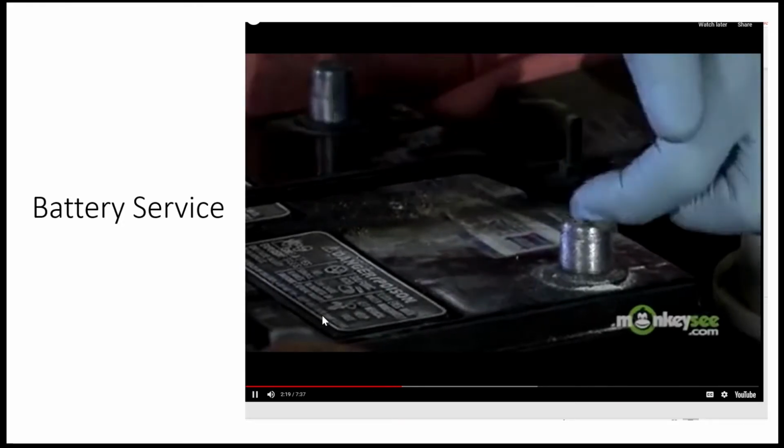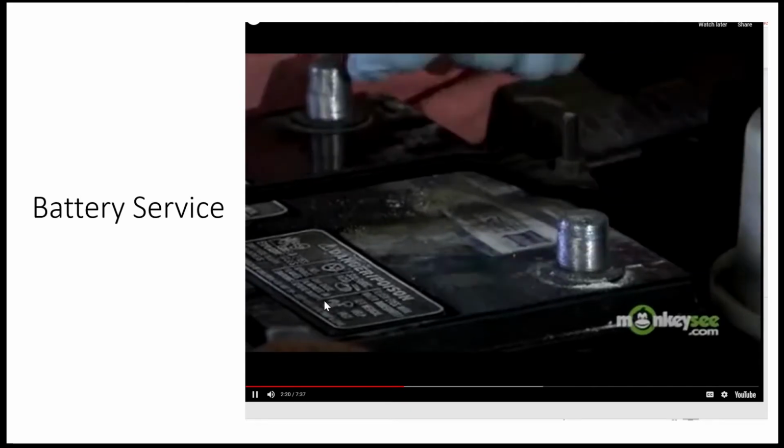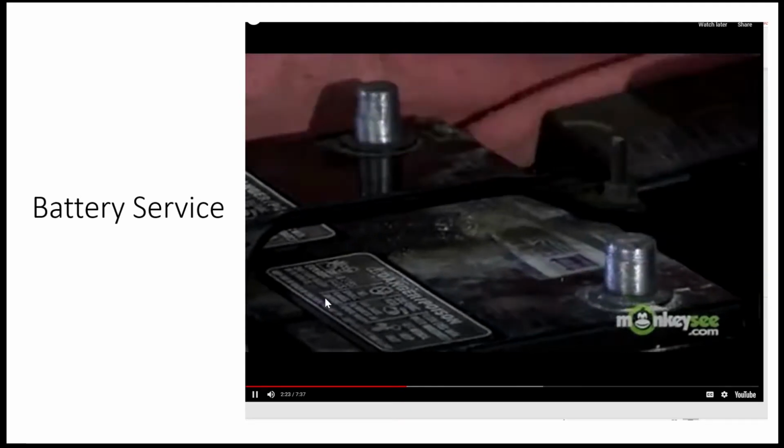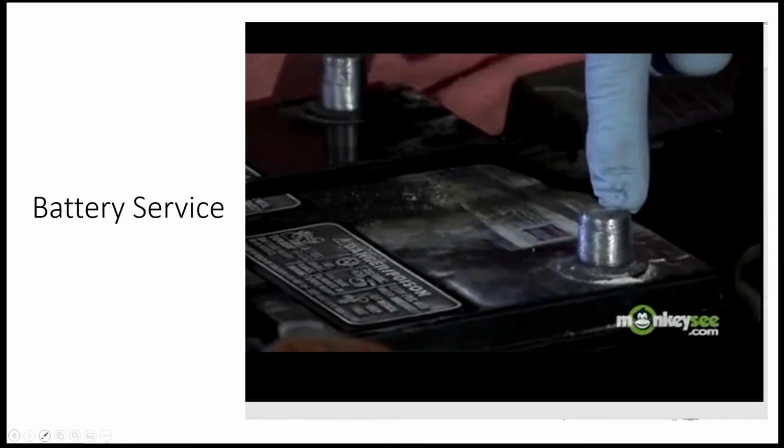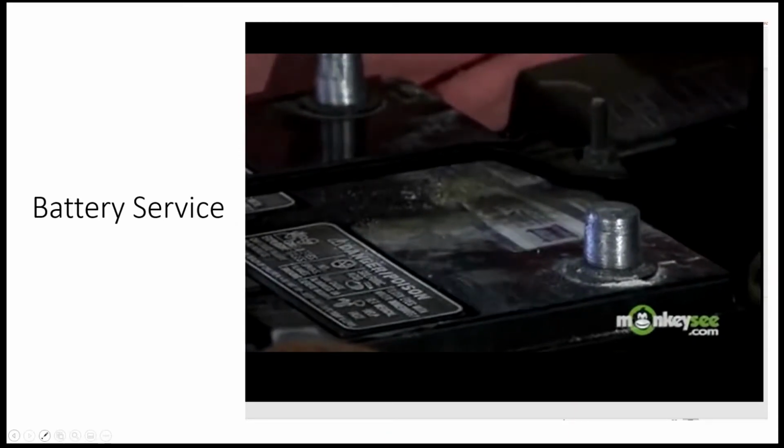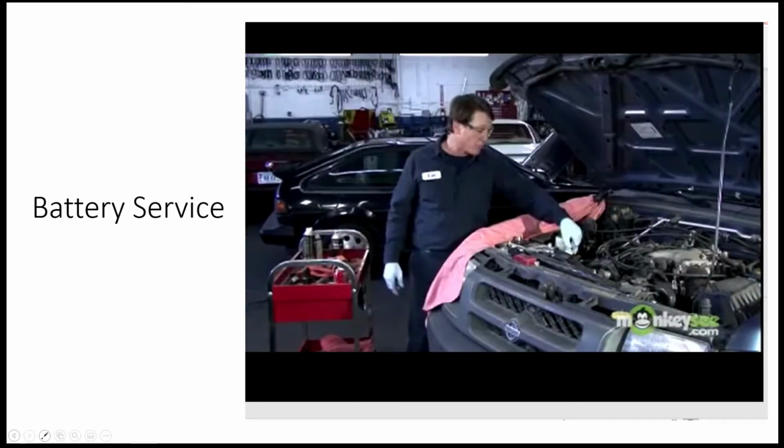As you can see, the post now is nice and shiny. They're made of lead, so you can tell when they're clean and when they're dirty. The top of the post is slightly discolored. It's not a contact point, so it's nothing we really need to worry about. All right, let's move on to cleaning the cable itself.